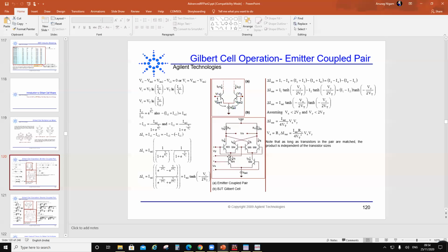One signal is varying the GM of the translinear cell. Then for the other signal, GM times RO is the gain of that stage. So GM is varied with Vx. GM is a function of Vx, and RO is going to be RC. That will be the voltage gain multiplied by the input Vy. That will be the output. So basically the 2 voltages get multiplied. Now this is a multiplier, which is as good as a mixer.